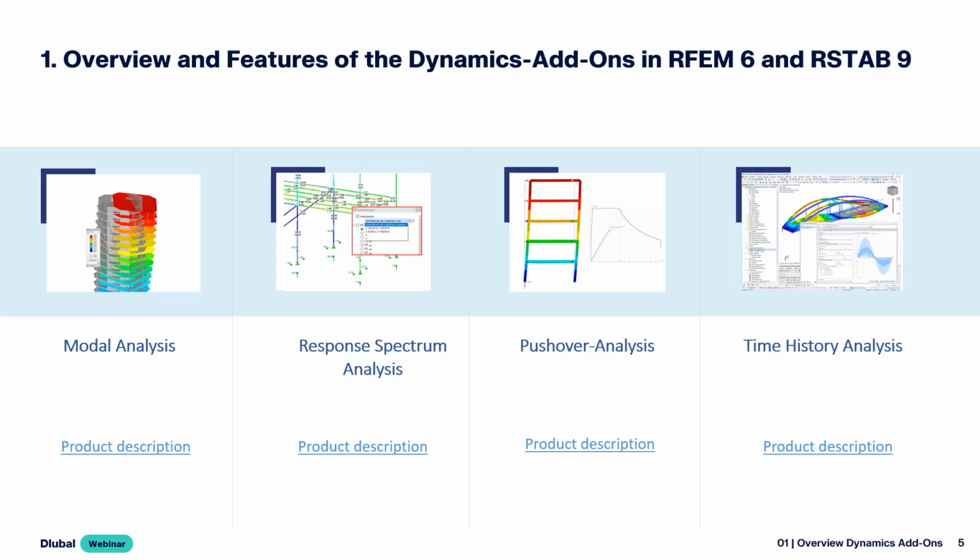First, it looks quite complex, but the theory behind it is, well, quite simple. It's two parts. The first part is just we will get the force deformation curve of the system under horizontal load. So the analysis is quite simple. We just push the system from one side until it either reaches a wanted point or it breaks.